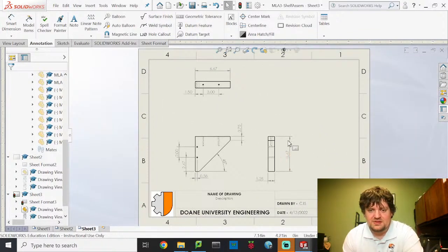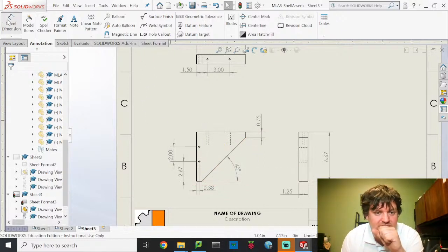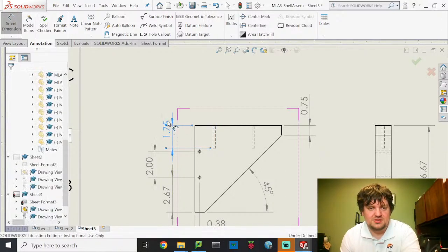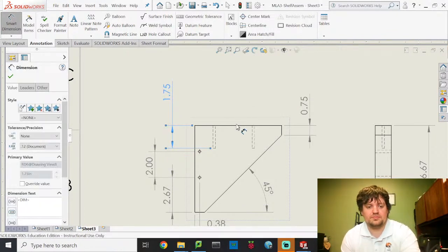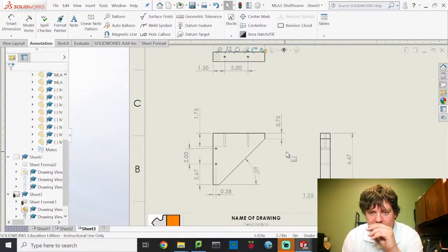And now my bracket piece. This is all the details you would need to build this yourself. Other than I need to establish the depths for these holes. I guess that's one last thing. Oh, and I didn't give, oops. Here, SolidWorks likes when you line up dimensions, so we'll do that. Okay, so it shows that that goes down a depth of 1.75 inches. Whereas these go all the way through.